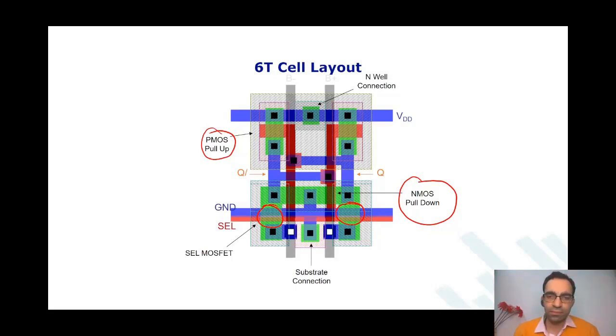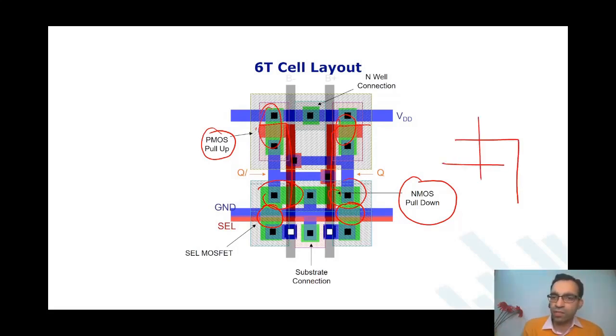Maybe lots of turning, lots of bends. Really, look at this, this poly is bending. The direction of PMOS and NMOS devices is different. There is a bend in the NMOS device itself. There are pull downs which are vertical, like this, and the passgate which is like this.